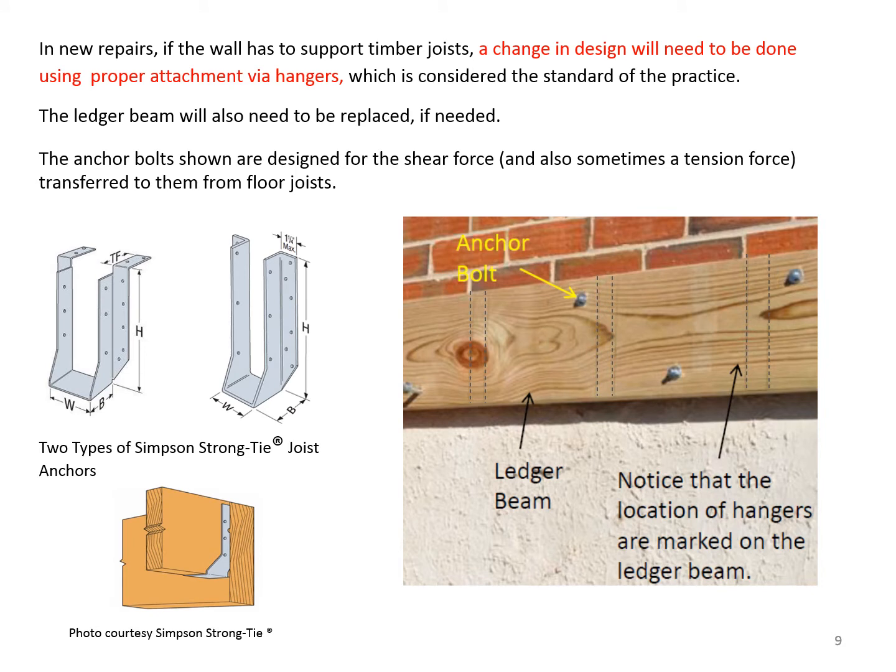The anchor bolts shown are designed for the shear force and also sometimes for a tension force transferred to them from floor joists. The figures to the left show you the hangers, and these are by a company called Simpson Strong Tie, commercially available for use.